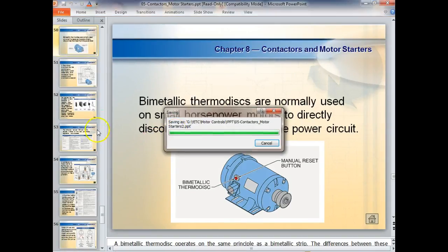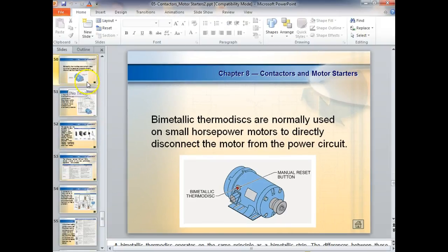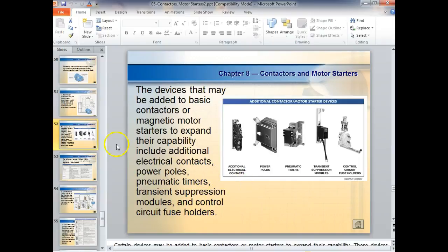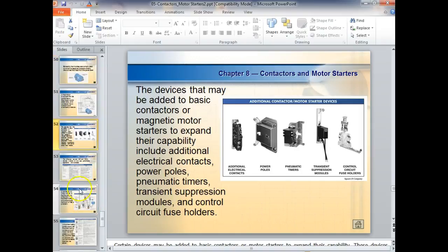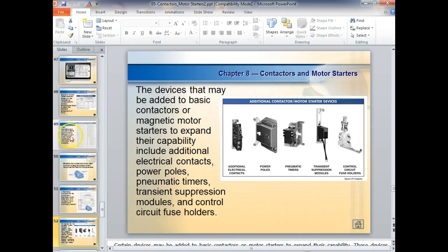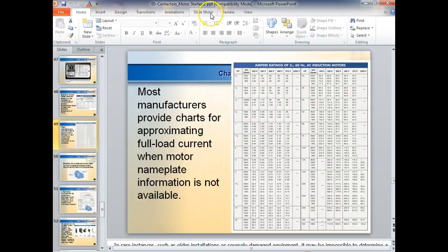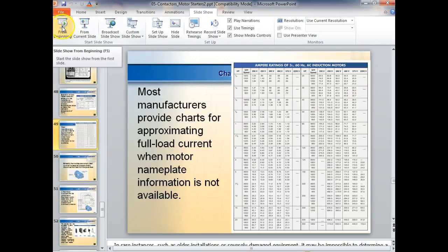So we make one revolution for one pair. If we had two poles, then we would make one revolution for two pairs, right? Does that make sense? So the more magnetic poles the motor has, the slower the motor runs. So anybody know the formula for the field speed for an induction motor?